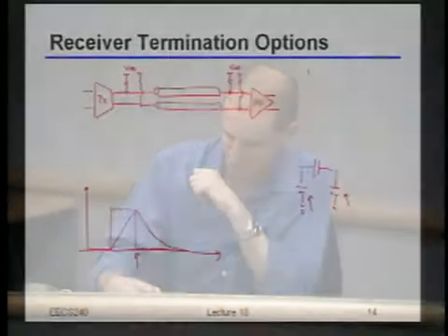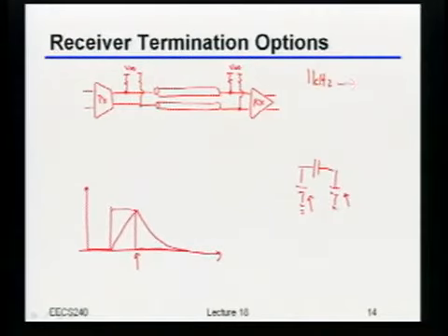Yeah, so for the bit error rate, when you do the noise calculations, you need to include flicker noise also, right? It depends on what differential pair you use. If the length is pretty small, your power will be... You may or may not need to. As usual, you should actually do the integration and see what makes sense. I don't remember, did I give you the lower limit of the integration or not? No. Okay, so I'll post that on the web. But I believe you should do it from about a kilohertz to, let's say, 100 gigahertz or so. So I guess it doesn't matter, no? Okay, well, by the way, how did I decide that I want a kilohertz?